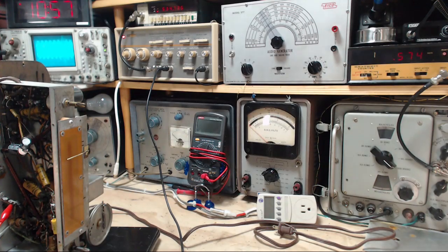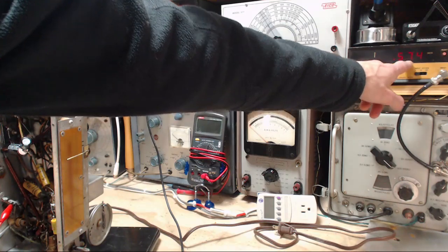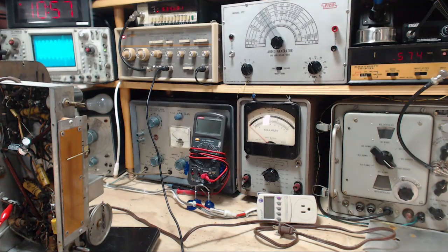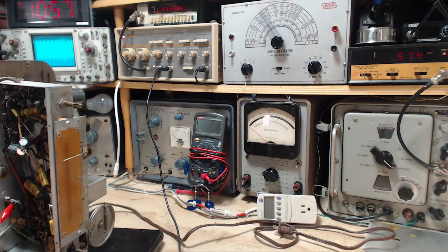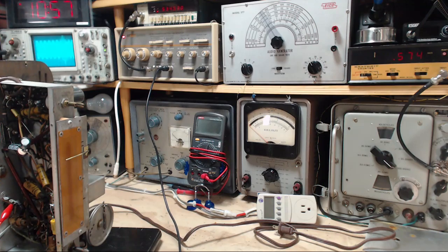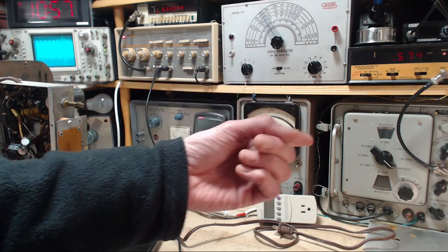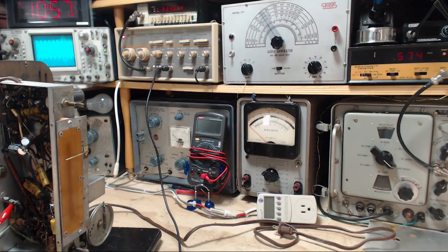Okay, I had a chance to do a little vacuuming in the house, and I see now this has settled down. 574 is where we're at. I'm thinking that should be 600. So what I can do is disconnect the equipment, run the radio, tune it into a known frequency, use the signal generator to make sure I get there. Reconnect the equipment, like turn off the radio, reconnect the equipment, and see if it still reports the same frequency. And what that'll tell me is whether my test setup is interfering with the radio's operation, and I really can't draw any conclusions from what I'm doing.